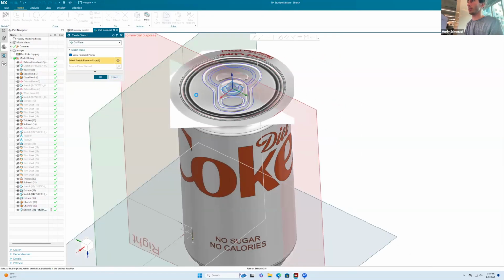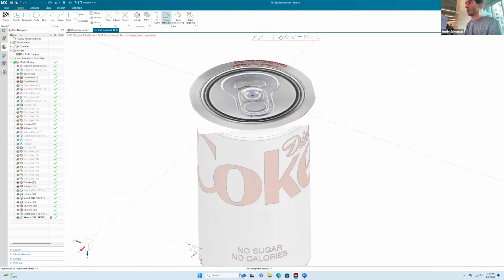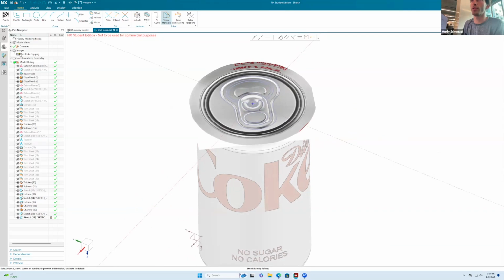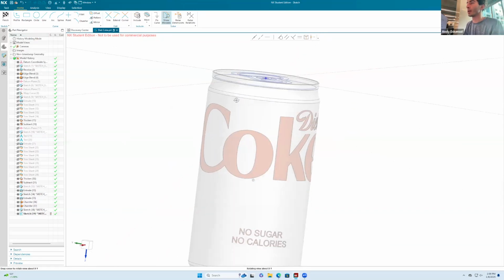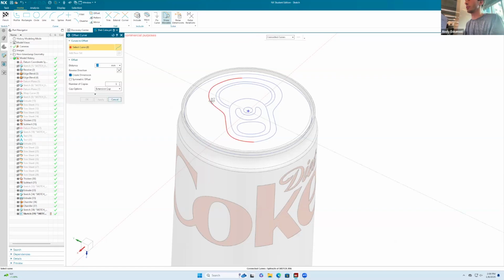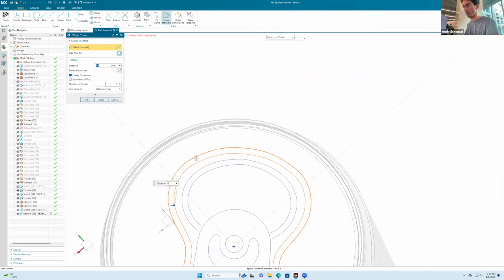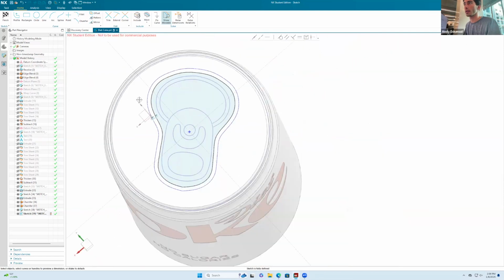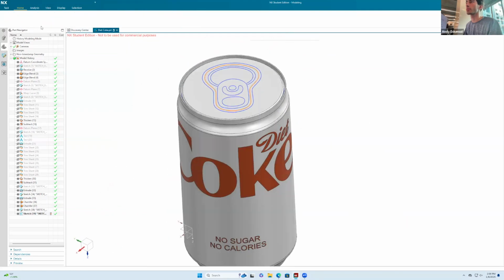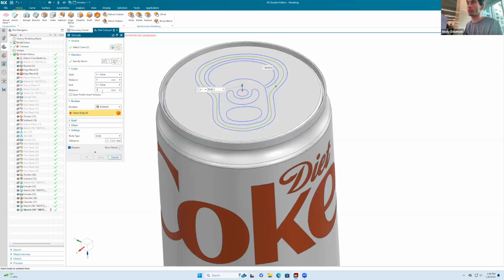Now we're gonna start a new sketch. Gonna be right here. And in fact, I can actually get rid of the picture, so it doesn't confuse us as much. So the first thing I'm gonna do is, let's see if I can offset all of this stuff inwards by -2. Yeah, is it okay? And now we are gonna extrude downwards, subtract -1 to the body here.